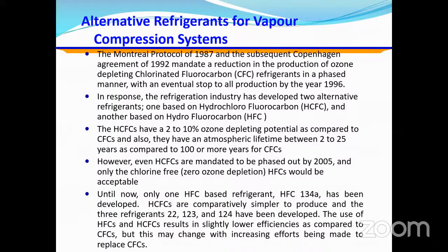HCFCs are comparatively simpler to produce, and the three refrigerants R22, R123, and R124 have been developed. The use of HFC and HCFC results in slightly lower efficiency as compared to the CFCs, but this may change with increasing effort being made to replace the CFCs.